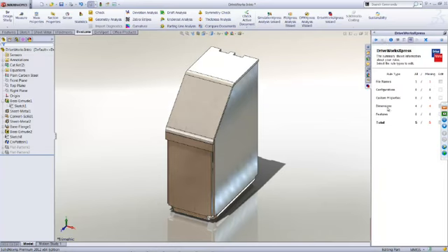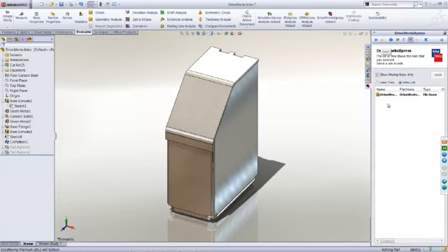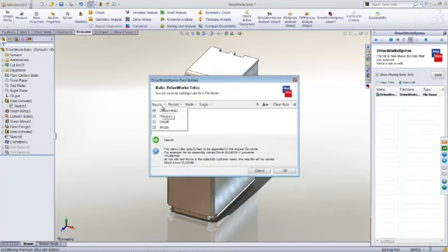And what the system lists down here right now are the different kinds of rules that are required based on the input that we have defined. First, of course, we need to have a file name rule defined. How do we want this piece of information to be created? So I check on the file name, edit, and do a next here. So what kind of file name do I want to create? I want my file name to have the customer ID, whether it's a number, alphanumeric value, etc., appended to the end of the file name.